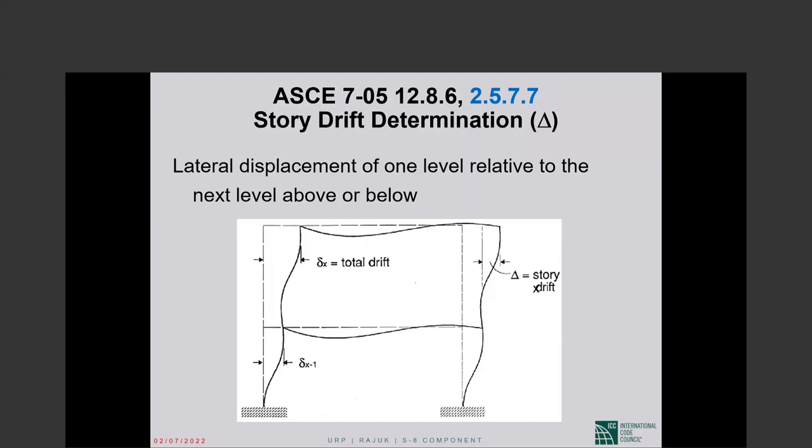Seismic design in our codes is essentially about life safety. Occupants will at least be able to escape before a structure actually collapses. That is pretty much our aim. We are not trying to minimize, we are not trying definitely to prevent damage to our structure or anything like that.